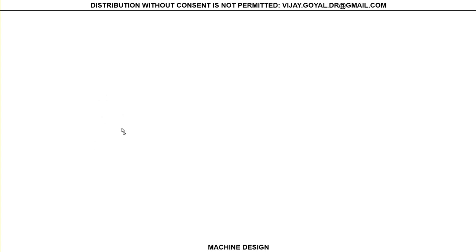Okay, and these are the stresses that you have. So you will have sigma 1 divided by sigma tensile minus sigma 3 divided by sigma compression. And you can see that you just use the absolute values there, right?